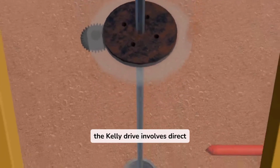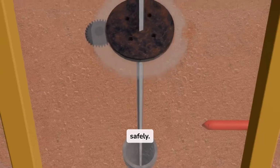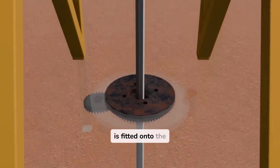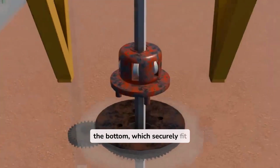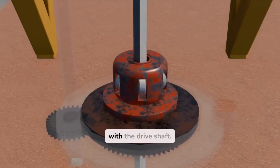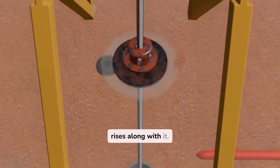While the Kelly drive involves direct mechanical contact, it is designed with robust cooling and lubrication systems to manage friction and heat safely. A Kelly bushing is fitted onto the Kelly rod. This bushing contains special gears that allow the Kelly rod to move up and down smoothly while still rotating. The bushings also have locks at the bottom, which securely fit into the drive shaft. Once locked, the Kelly rod rotates safely along with the drive shaft. First, the Kelly rod is lifted upwards, and since the entire drill string is connected to it, the string rises along with it.